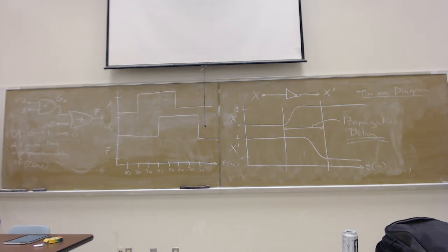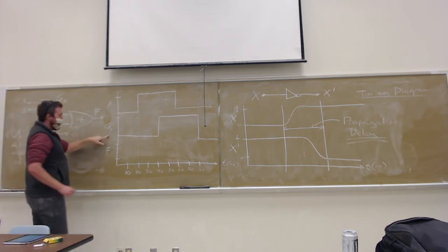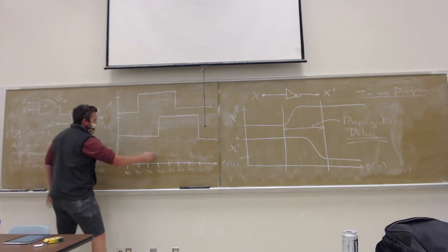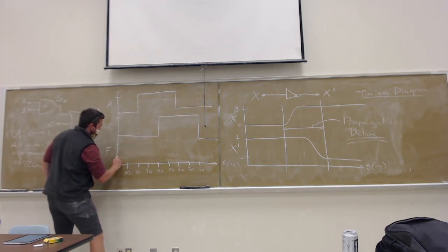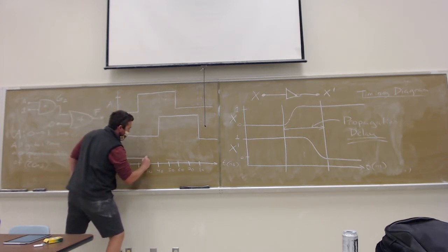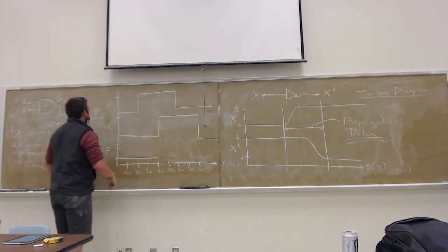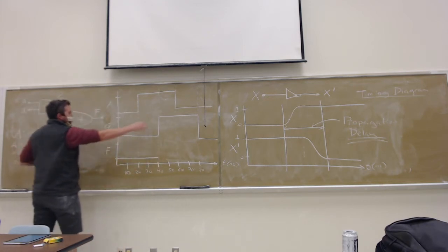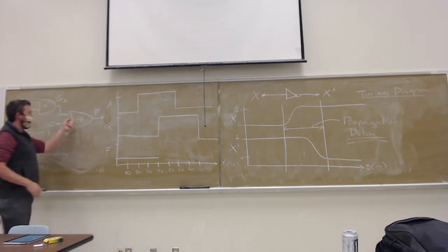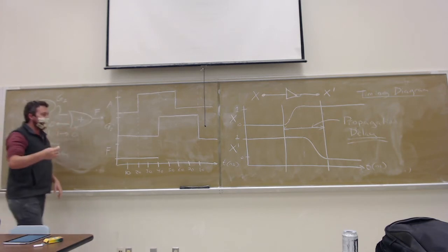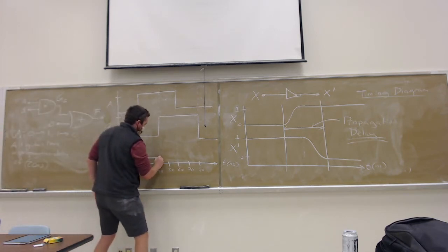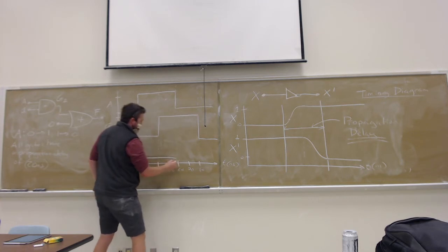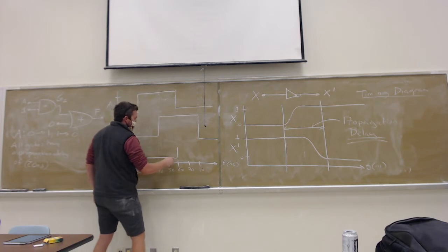Now, if we take a look at the OR gate, or excuse me, the output of the OR gate, our actual output function F, it's ORed with 0. So we had 0 and 0 all the way until at least here. And then we had 0 and 1, which means that the OR gate output becomes 1. But again, this is going to wait until 60 nanoseconds to click up to 1.